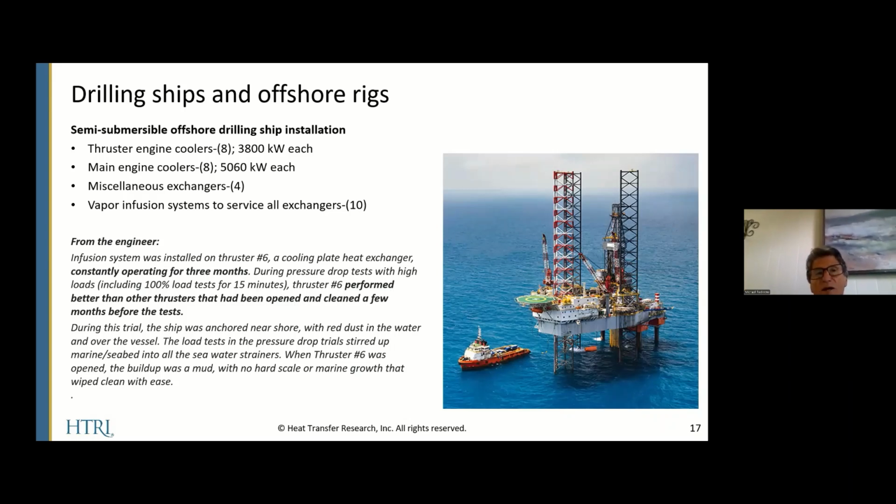Now, the interesting thing about this, having a significant heat exchanger profile, you would think that the infusion of chemical treatment would reflect in a residue within the effluent. The reality is that with all heat exchangers functioning at the same time and being infused, when they look at the total effluent of chemical treatment, it's well under 100 parts per billion for this entire system during infusion. And again, keep in mind that when there is no infusion, there is no residue being imparted to the flow water itself.